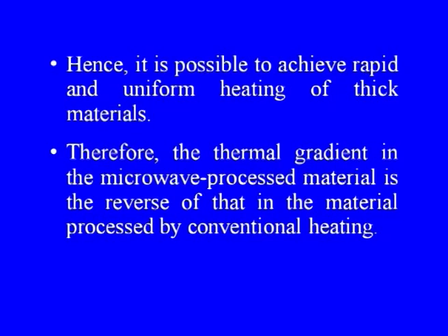Otherwise, either the energy will pass through it or it will totally reflect back without giving any chance to work with, that means hitting it or doing some other work. Hence, it is possible to achieve rapid and uniform heating of thick materials as well. Therefore, the thermal gradient in microwave processed materials is the reverse of that in the materials processed by conventional heating, which I have already shown as outside in and inside out concept.